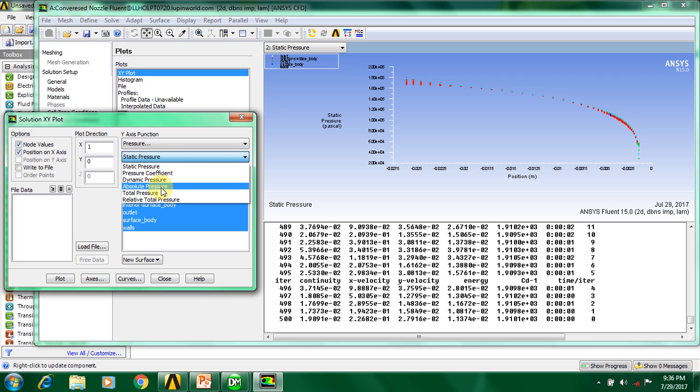Thereafter the pressure is constant. If we divide this pressure by this pressure, the value should come 0.53 to 0.57. That is the critical pressure ratio, and that is also the condition for sonic velocity at the throat.